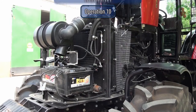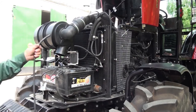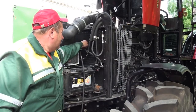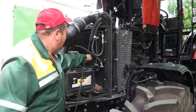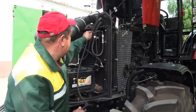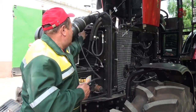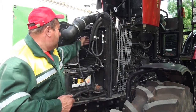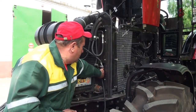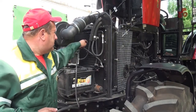Operation 10. Inspect clean air conditioner condenser. Check cleanness of the engine radiator core. In case it's clogged, clean it with compressed air. Airflow shall be directed straight to the conditioner downwards. Greased ribbon must be straightened with a plastic or wooden plate. In case of severe clogging, rinse it with hot water under pressure no more than 0.15–0.2 megapascals and blow it with compressed air.